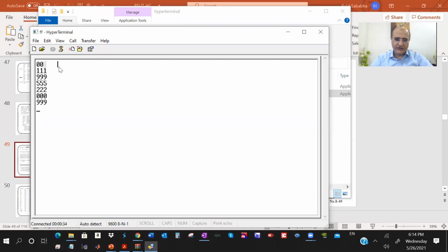I can add the 4th digit. This is the concept. If you put an LED, you'll see it changing its brightness. If you put a motor, we're varying the pulse width. And you're going to be changing. This is pulse width modulation, but using the output compare. But since the time we're staying low is 1 millisecond, for motors, this is not enough. Anything over 2 is reasonable, but 1 maybe is, or in micros, is not going to be enough.